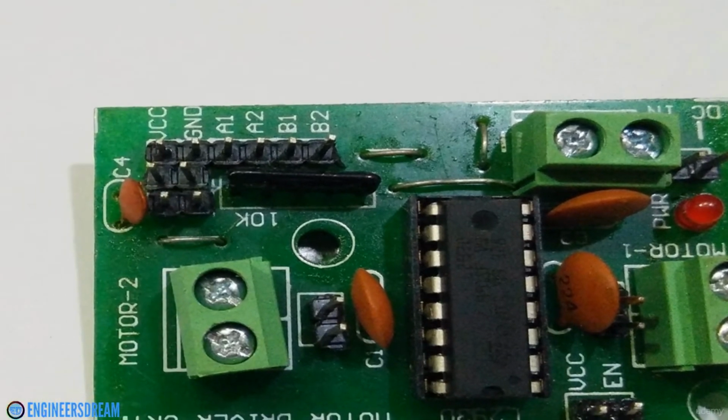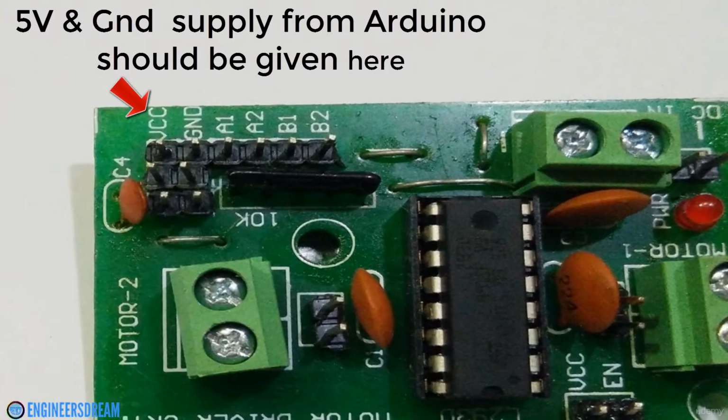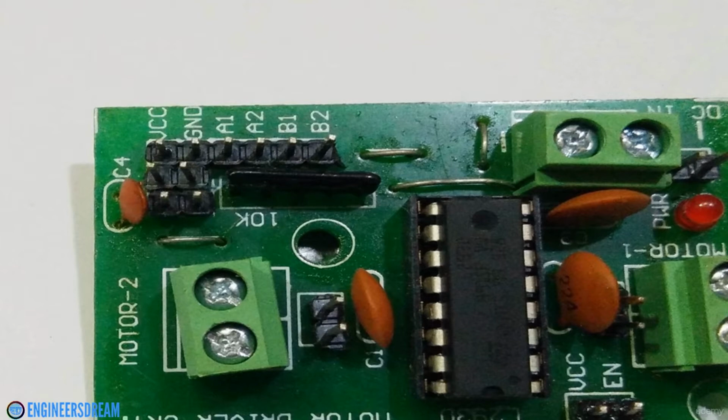Now, if we look closely, there are 2 more pins for VCC and ground. At the VCC pin, we had to provide a supply of 5 volts from the Arduino. That is, I had to supply power from the 5 volt pin of the Arduino to this VCC pin. And I also had to connect one ground pin of the Arduino to the ground pin of the motor driver. So guys, the disadvantage that I found of using this motor driver is that I also had to give 5 volts of supply from my Arduino to the VCC pin of this motor driver.